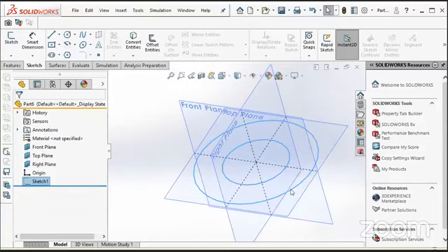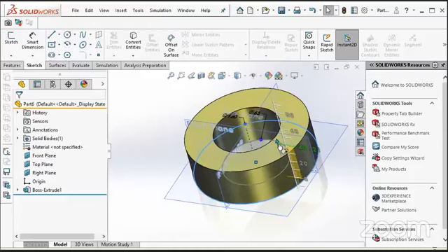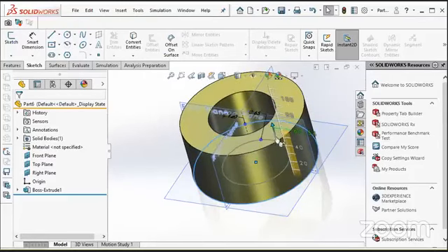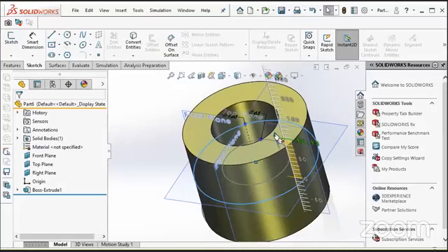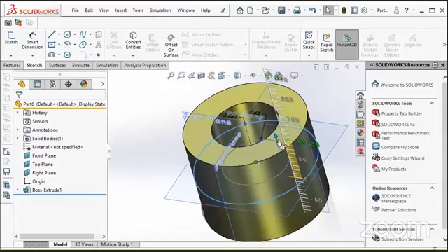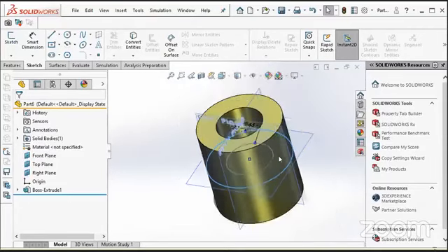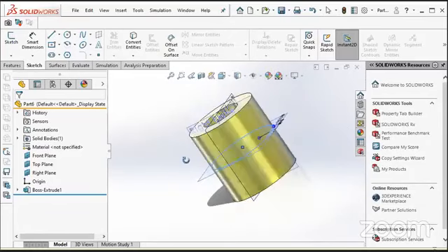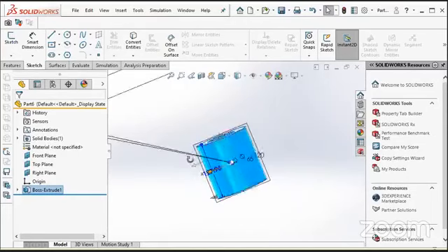I will simply double click and drag my reference sketch to give it a protrusion. So as you can see on the screen that it is a one-sided protrusion. When I click on M, it will give me the protrusion from the midplane. So I will set the value to, let's say, 127. But this is not an issue. When you are not exactly defining your value, you can double click on your part and give your value.